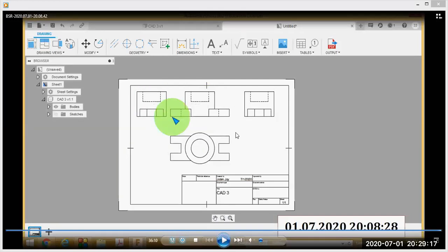So you can see the front view. I will write here, this is the front view, and this view is the top view, and this view is called a left side view. Sometimes you may think that when you are dealing with your notebook, this side will be your right hand side. Okay, so this is actually first angle projection.